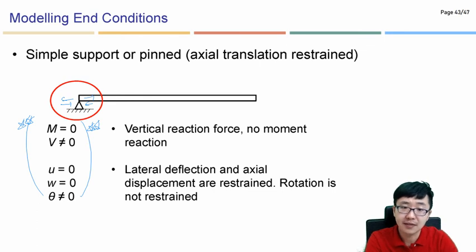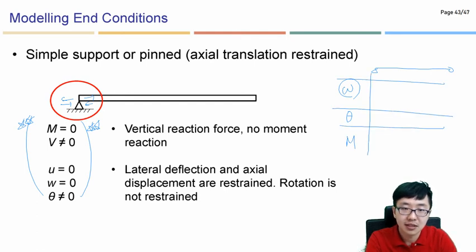Have a look on these kind of boundary conditions. And previously I have introduced many times about, for example, simply supported condition, deflection, slope, and moment. Do you remember? Like simply supported and clamped condition, and deflection case at here A and B, deflection is this way, it should be 0, no deflection. In the case of slope here, because this is simply supported condition, so slope is maximum.